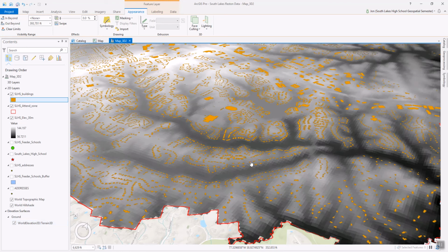I think its resolution is changing depending on how close we get. So the farther out we are, it uses larger raster pixels. If we get in closer, they seem to get smaller, and I don't see the resolution deteriorating. But if we use our own digital elevation model, as we zoom in on it, those pixels become very large. 30 meters is big.